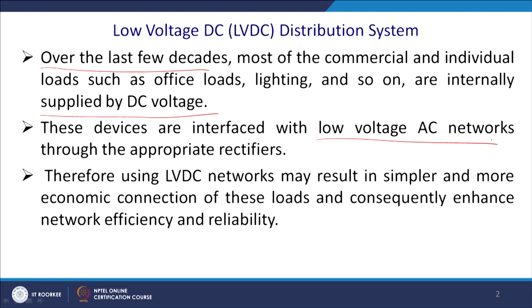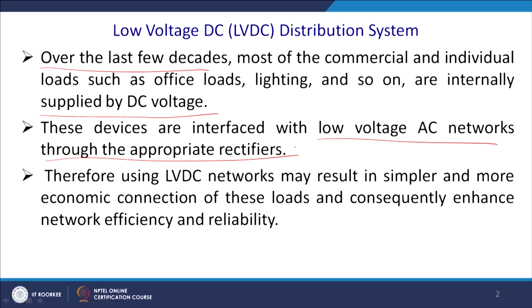Otherwise you may just convert AC to DC by a rectifier, say a 6 pulse converter, and thus you will inject a sufficient amount of harmonics into the system. And for this reason, nowadays we are putting a restriction: once you are converting AC to DC, you have limited restrictions on the THD also, and thus a simple diode bridge rectifier cannot serve the purpose.